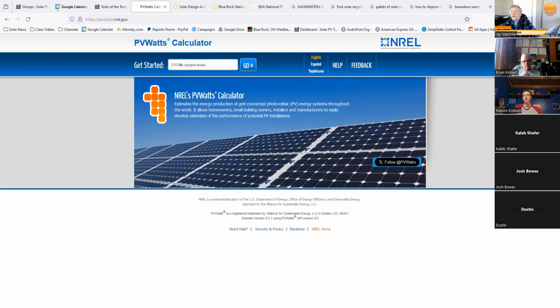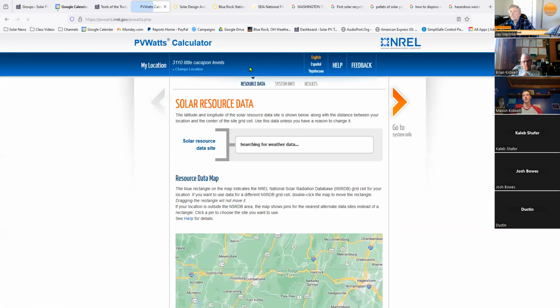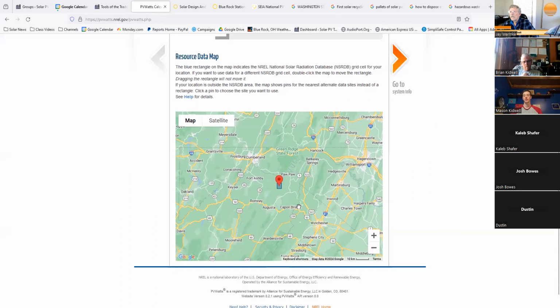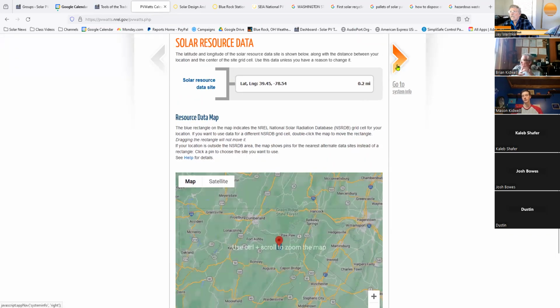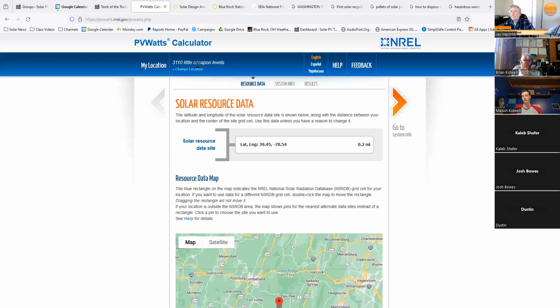Jay, can you hear me? Yeah. This is Josh. I was wondering, so I'm a little bit ahead. In the derate, the online course mentions obstruction or debris, dust, stuff like that on the panels, and derating for that. Do you just automatically make that 1% when you're coming up with your system, or do you do it based on where the system is?